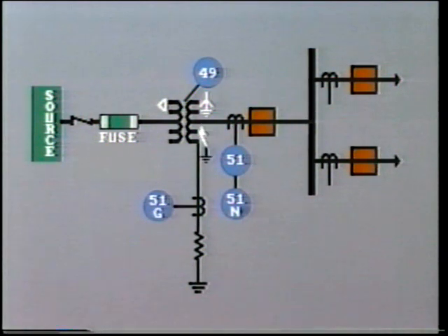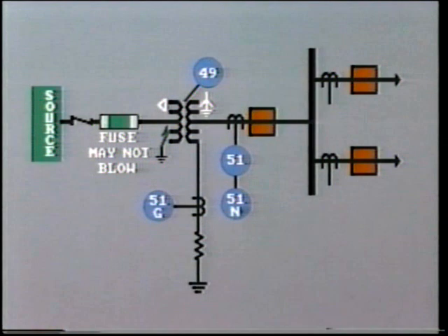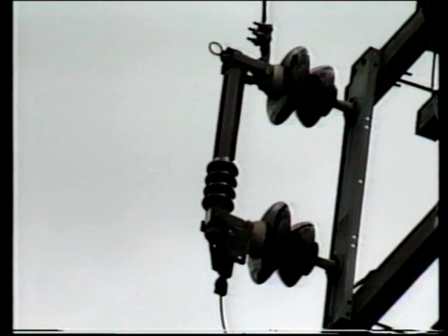As we mentioned before, a low-level ground fault on the secondary side may not be sufficient to blow the fuses on the primary. In fact, these fuses may not even blow for a ground fault on the primary, as the delta winding is ungrounded. The real function of the fuse is to protect the primary windings against a heavy phase-to-phase fault within the primary winding.